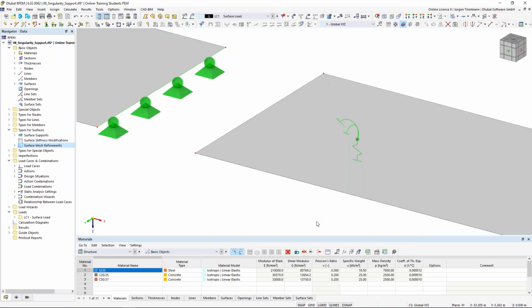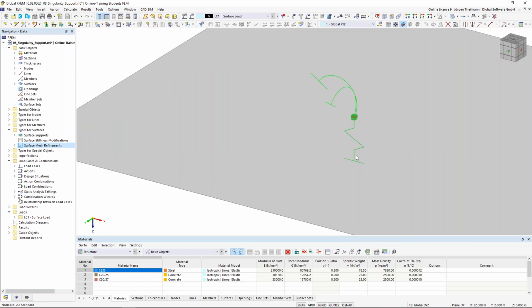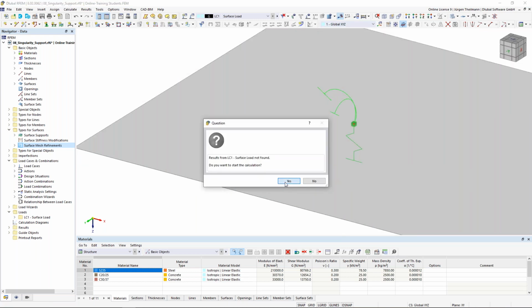And now you see this looks pretty different. So it has now a spring coefficient in all the 3 degrees of freedom we have for our 2D model right now. Remember that, still a 2D model with 3 degrees of freedom. And all those supports come with a spring stiffness. So I will calculate this again now.